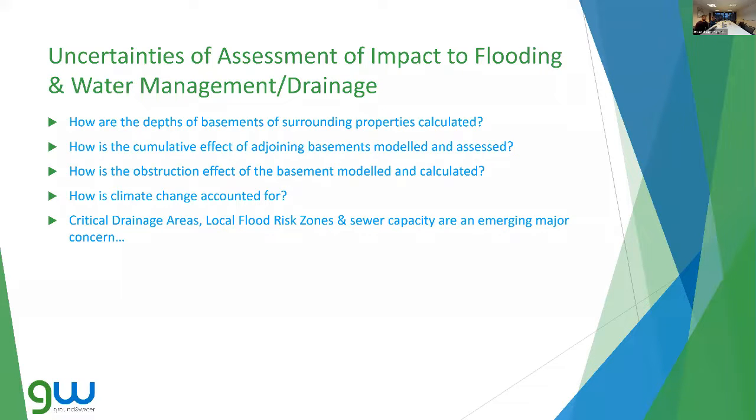Whereas in somewhere like Westminster, where you have gravels over clays, there's obviously an aquifer there, and any basements can act as obstructions to the flow within the aquifer. So even though there are only a few geological formations within London, the issues revolving around them can vary quite a bit from site to site with regards to flooding.